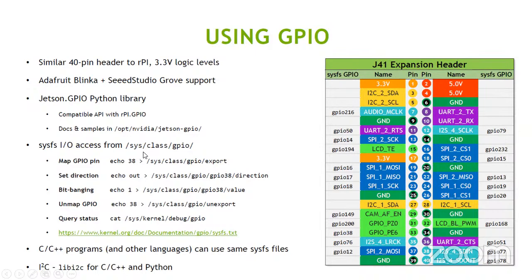This is one example of hardware abstraction. We talked about hardware abstraction yesterday when we were talking about ROS. In Linux systems, this is how we access hardware elements: as a virtual file. If the file is saved in sys class GPIO, we can just change different configurations in that file and use the GPIO pin. You can access this virtual file for configuring the GPIO hardware pin.